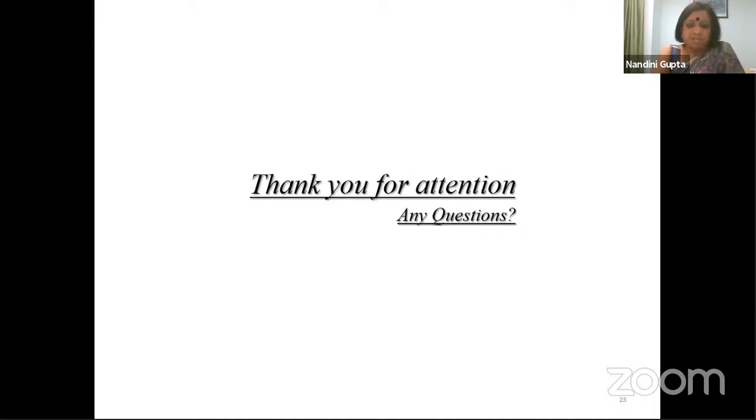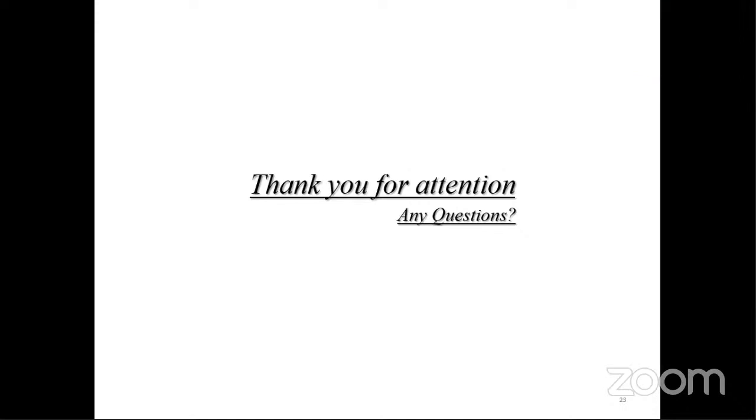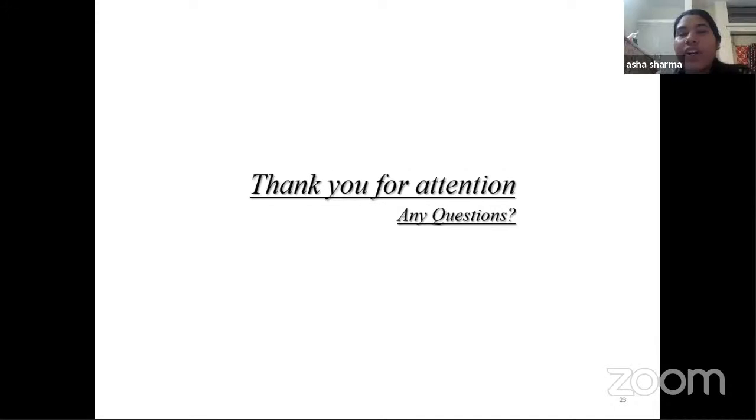In the question answer, there was a question from Raju Midya. Raju, you can ask the question. Hello, ma'am. Good afternoon. Good afternoon. What is the basic difference between puncture and flashover in an insulator? Okay, puncture means breakdown of that particular insulation unit, whereas flashover means the surface discharge. It is not taking the path through the solid material of that insulating unit. It is taking the air as a path from the high voltage electrode to the ground electrode. So it is actually not the breakdown of the insulation, it is the breakdown of the air, the flashover.